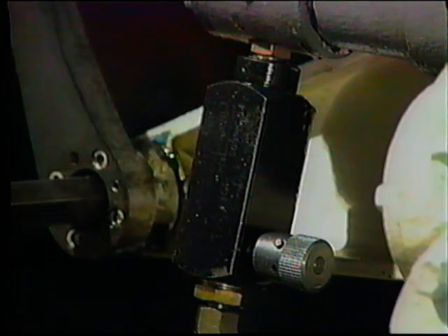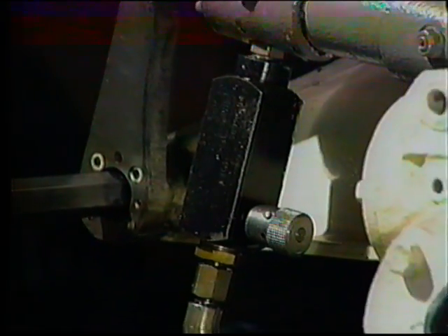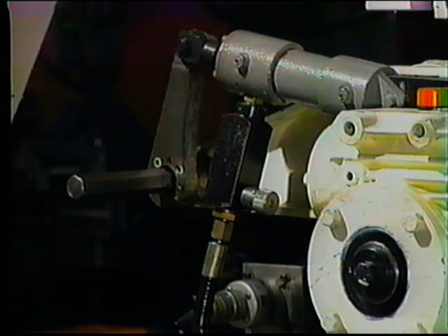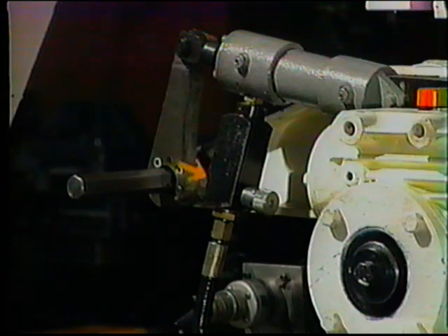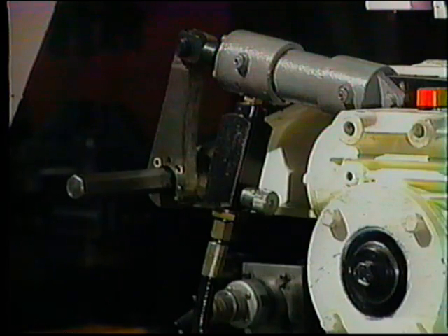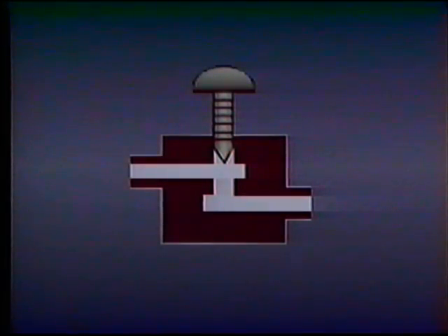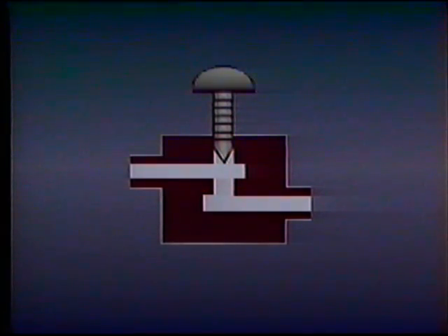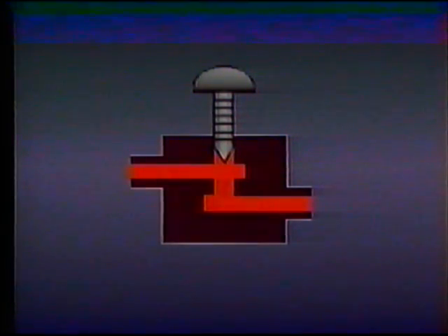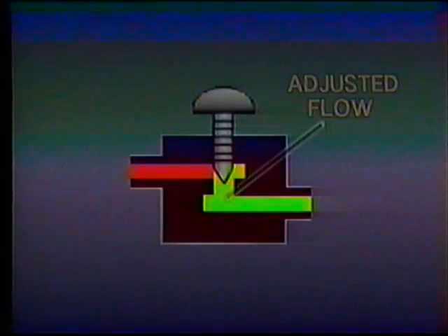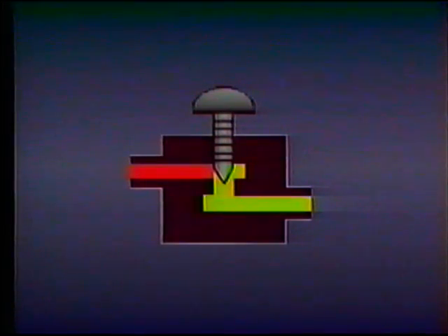Flow control valves are used to adjust actuator velocity by adjusting the flow rate to different parts of the system. These valves consist of a valve body and an internal part which moves in and out of an orifice. In one of its simplest forms, a flow control valve has a threaded rod with a tapered nose or needle which can be adjusted in or out to change the flow. Adjusting the needle varies the flow restriction, increasing or decreasing the flow rate through the orifice in the valve.